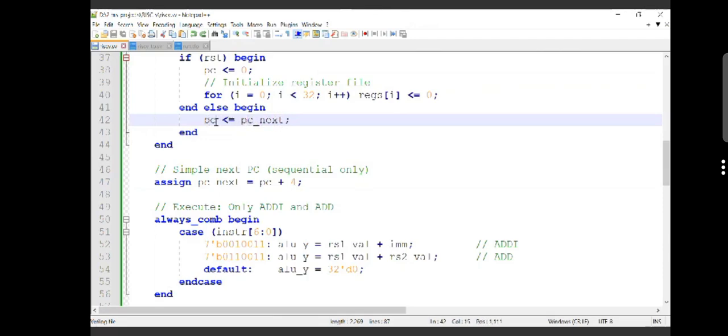So now the PC value will become 4. Now again it will substitute 4 here. Again 4 plus 4, 8. So now it will update with 8. Again PC will update with 8. Again 8 plus 4. How many times will it repeat? Until you reach your 31 locations, it will continue sequentially, serially doing this process.